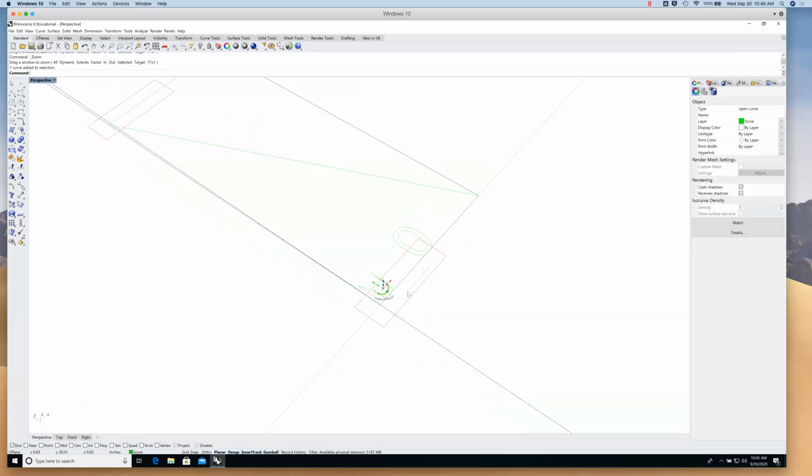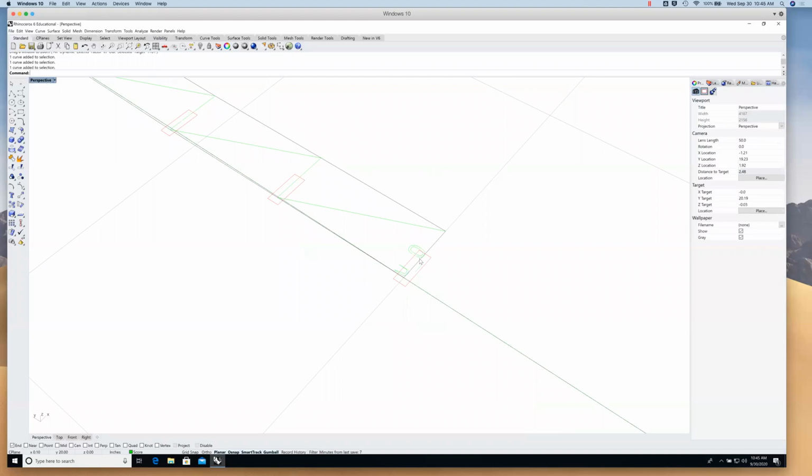Not sure what it's doing. It's really butchering this poor U and V. That's weird. Maybe I'll try to find a mono stroke font for you guys to download and use. That way, it minimizes the amount of X and Y travel just to engrave these things, right? Because if you have to go around the whole outline of a number and a letter, that's just more cutting time, and the less cutting time, the better, right? Because that's money and time.